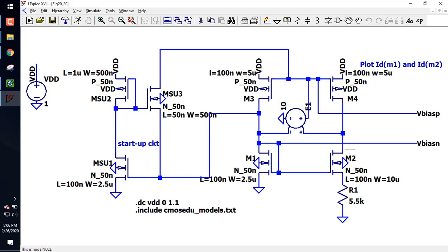This goes down by 2 volts and this goes down by 1. When I do 2 minus 1, so this is minus 2 minus minus 1, I get a net change of minus 1 volt, times 10 means a net change here of minus 10. Because this is going down faster than this one. Kayla, you look perplexed, so let me try it again. Right, so one more time.